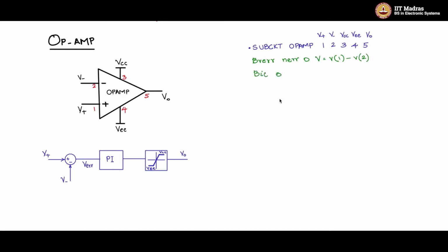And then if I have another virtual current source, a B current source between these two nodes, 0 and NIC, again two virtual nodes, where this B source now acts as a current source, and therefore I say the current value is proportional to or equal to VERR, which is the voltage across this node, NERR.